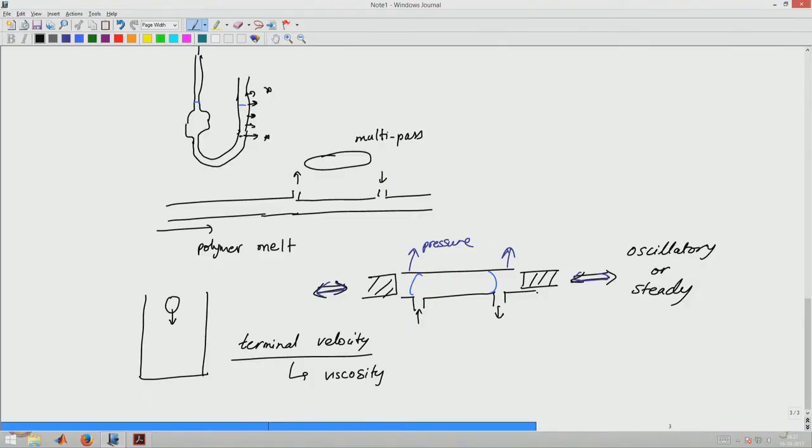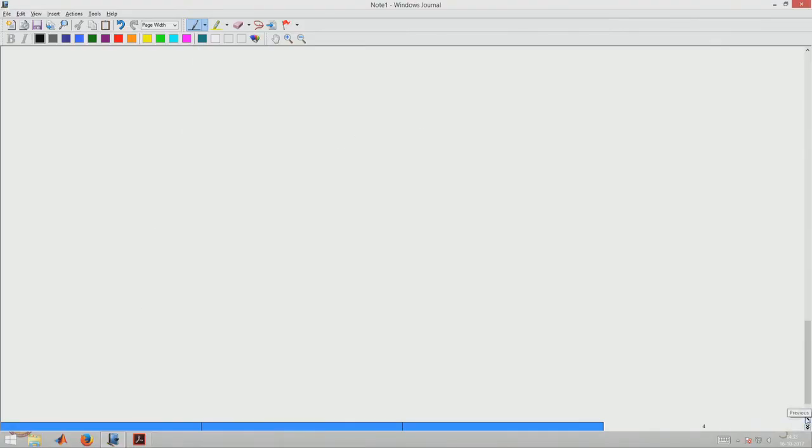The main problem associated with rheometer instrument design is the fact that we are applying some torque or some force. So, let us say the cone which is being used to rotate, and the plate which is there, this cone is being rotated at a certain rate and the motor has to be used to do this rotation, and whatever is happening to the cone has to be in a precise manner. So, the motor should be able to apply the torque, because the motor will require certain torque for its own rotation, and then it requires torque over and above that for this rotation.